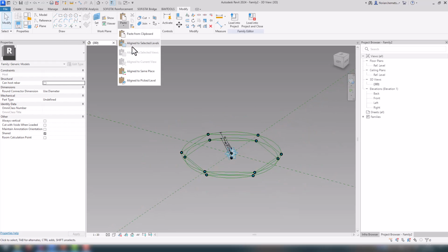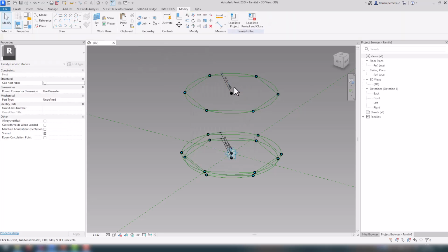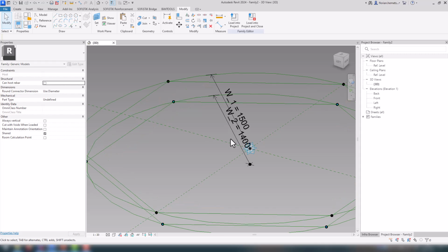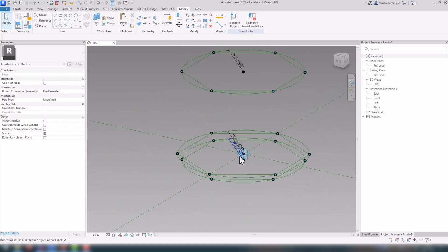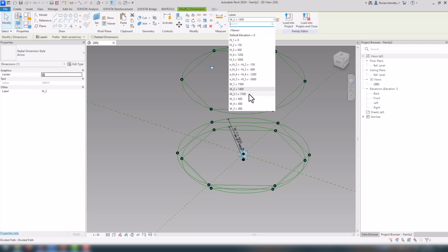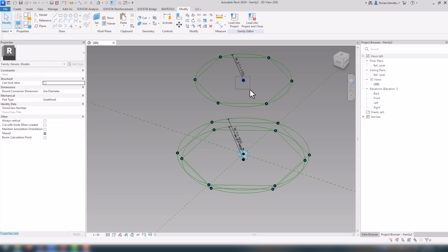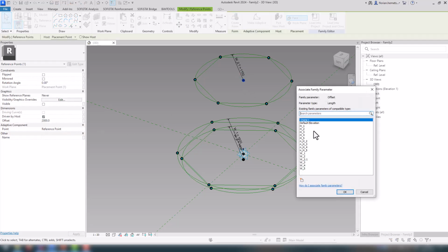We will keep pasting these references that we already created, and keep in mind at width or at height number 2 we want to have a jump in there, meaning that we change this one to width 2.1, but the offset from our reference plane is still H number 2 or negative H number 2.